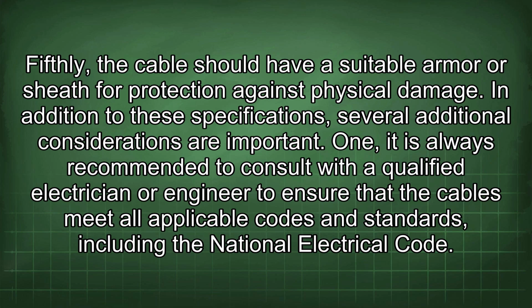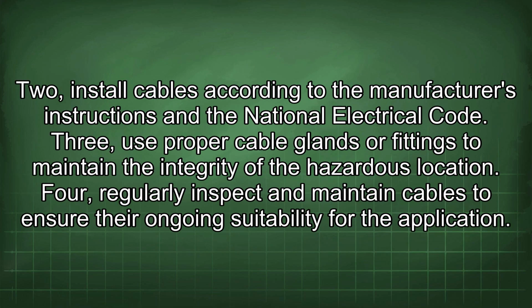1. It is always recommended to consult with a qualified electrician or engineer to ensure that the cables meet all applicable codes and standards, including the National Electrical Code. 2. Install cables according to the manufacturer's instructions and the National Electrical Code. 3. Use proper cable glands or fittings to maintain the integrity of the hazardous location. 4. Regularly inspect and maintain cables to ensure their ongoing suitability for the application.